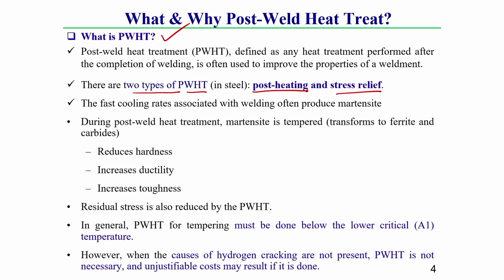Why is this post weld heat treatment process or stress relief post heat treatment process required? Everything I will discuss in detail. Generally, we do this post heating to reduce the chances of cold cracking, whereas the stress relief post weld heat treatment process is also mainly used to minimize weld induced residual stresses.